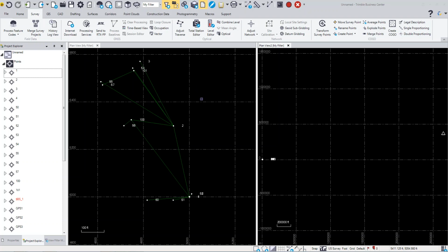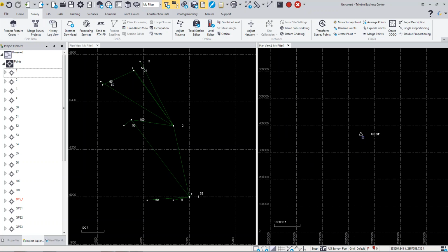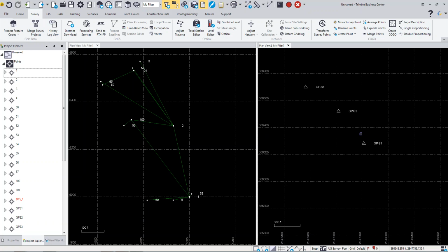The transform survey points allows you to move survey points from one location to another. A typical example would be that the survey crew went out here and collected this data, and you can see based on my coordinates that they just started with an assumed coordinate, and they put in a couple control points and some flies. Then they went out and GPSed in the points, and now I've got good control points